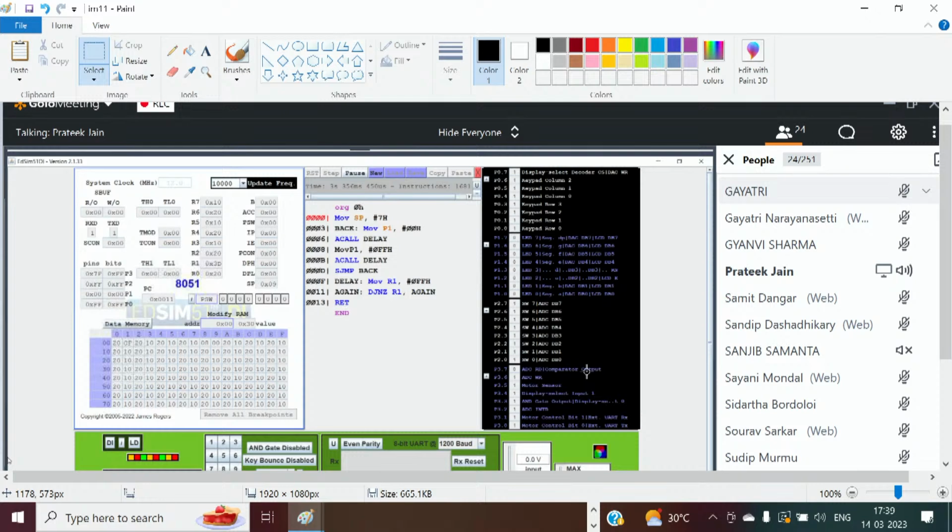One important point is that if you touch or interface the port with a CRO, then we can see the square wave. So from this 8051, we can generate the square wave, and this is one kind of interfacing application also. Tell me or tell Amarjit sir if you have any doubt.